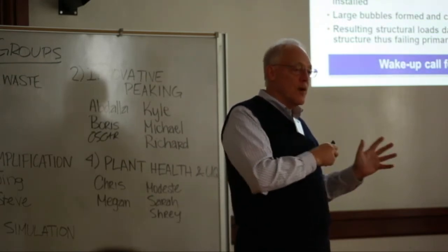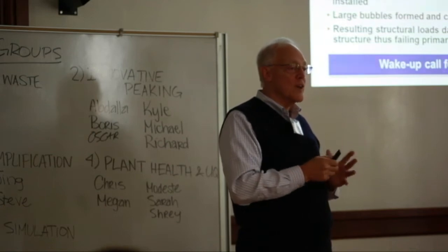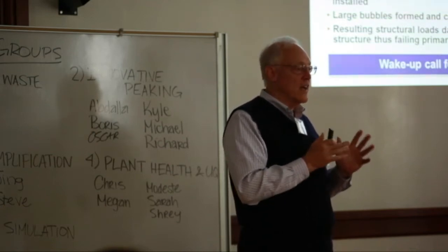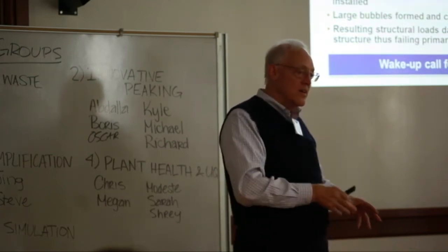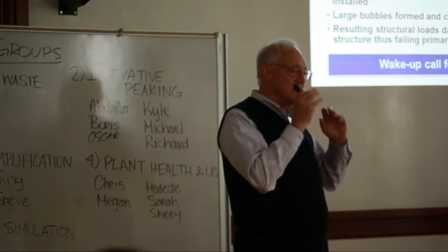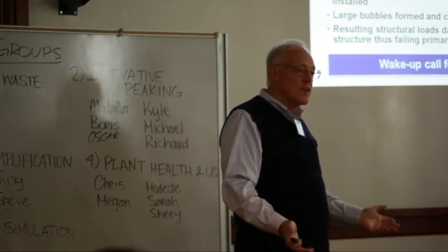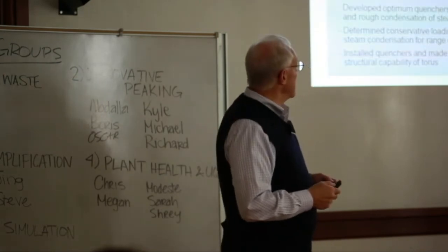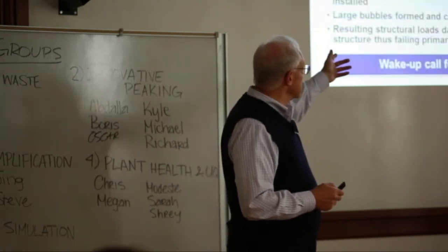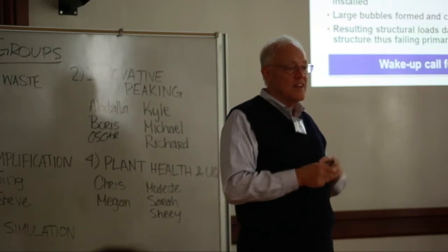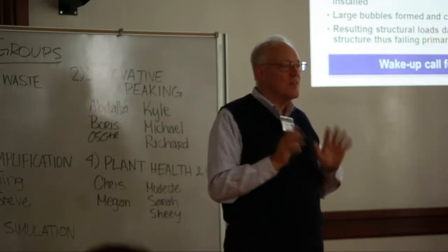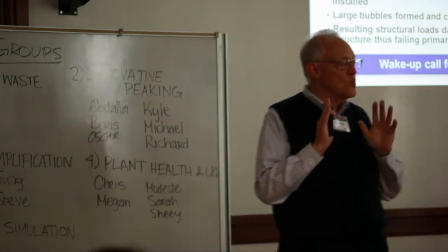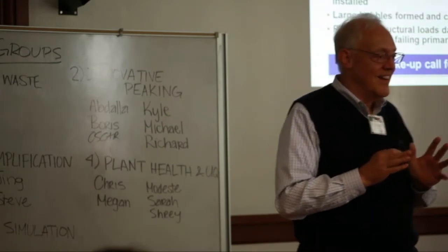GE and its counterpart in Europe had never really gone through a full analysis of what happens when I dump air, I dump steam, I condense it in this water, and what do I need to do about that? There's a fix to this. You basically do what's called a T-quencher on the end of it. You distribute the energy. You can fix it. The question is, why didn't you think about it initially?